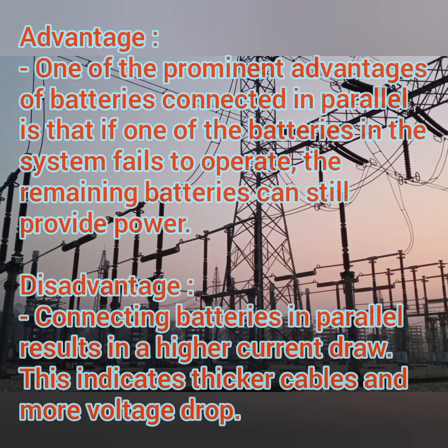The second thing is that connecting batteries in parallel results in a higher current draw. This indicates that we require much thicker cables for connecting this parallel connection. This is the main drawback of your parallel connection.